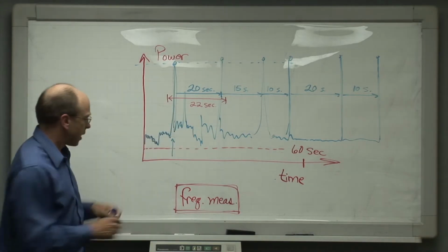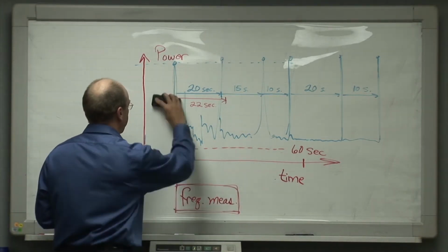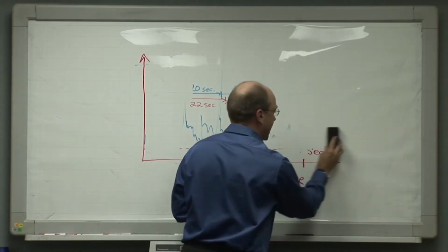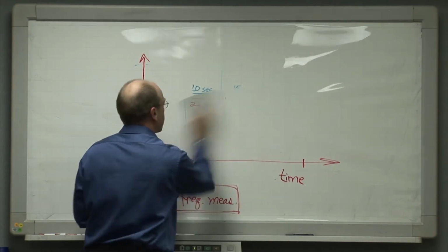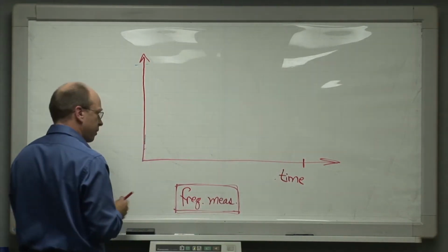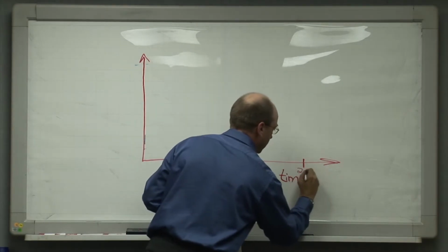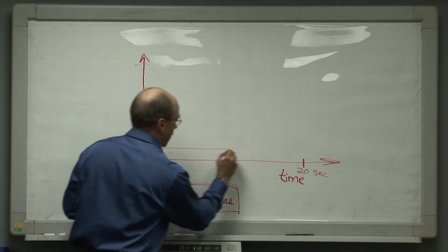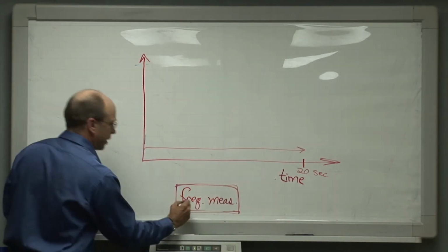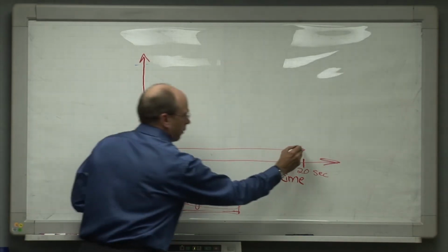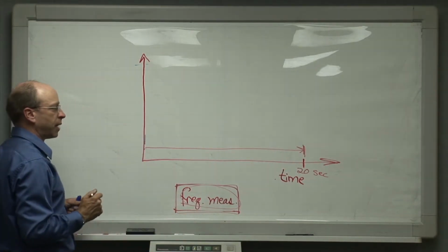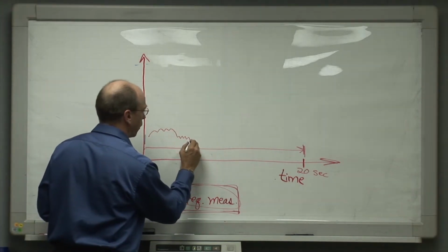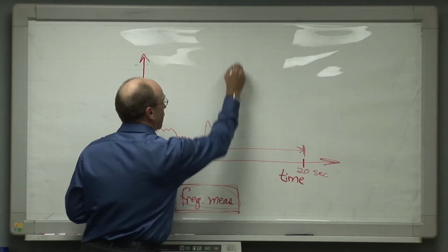So now we know that if we were to set up our spectrum analyzer in that stepping algorithm mode that I just discussed, which solves the dynamic range problem because we can keep adjusting our dynamic range as we step across, we also know that if we set up our spectrum analyzer for this particular radar such that it sweeps in time on a single frequency on which we're making a measurement for this magic interval, which we determine by watching the radar emission for a few minutes, then we know that at some point, we don't know which point, at some point in there, it's going to do that,